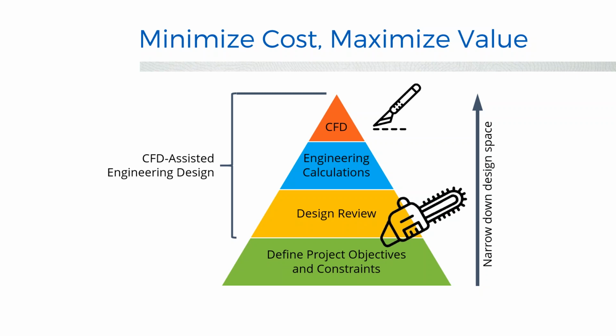So to effectively perform CFD assisted engineering design, you must first use simpler analysis to narrow down the design space and then apply CFD only to a limited number of scenarios where it will yield valuable results, which will inform the design and then help drive your project forward.